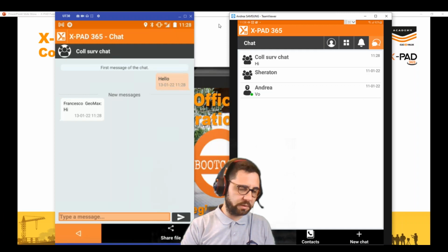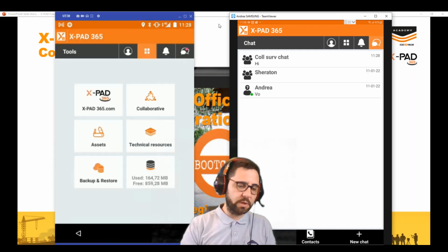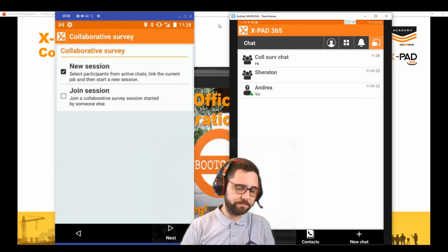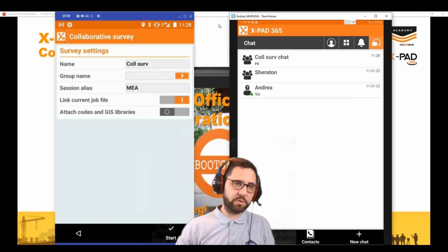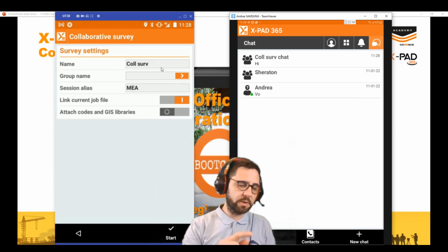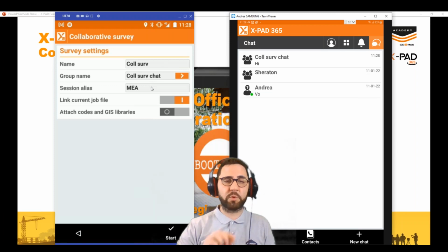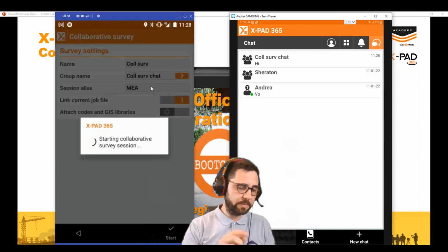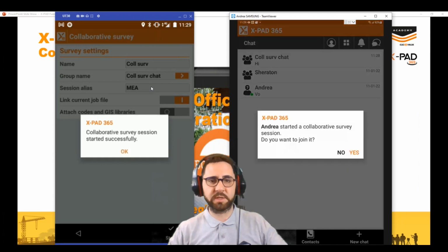In that case, I just want to create a new collaborative survey. So collaborative, new session. Here I need to enter the name of the collaborative survey session and select the group chat. The alias is important because from the alias you can directly check which points are measured by the first surveyor, which points are measured by a different surveyor. Okay, starting the collaborative survey session.